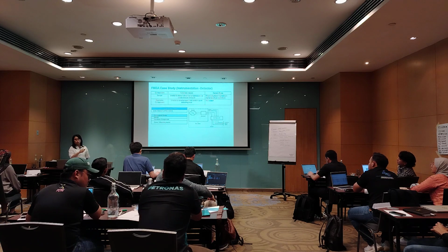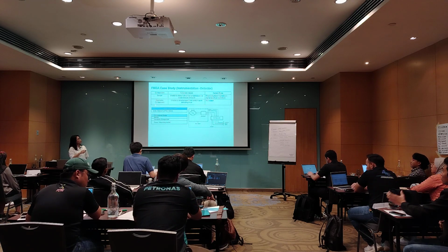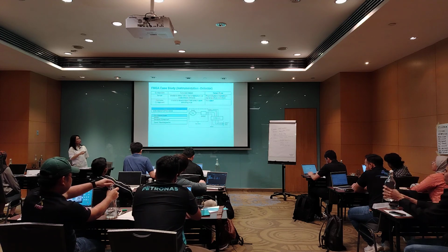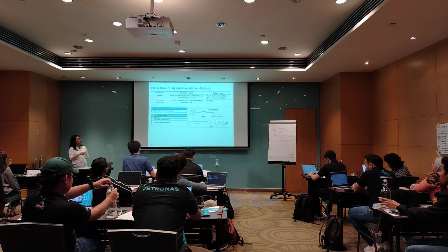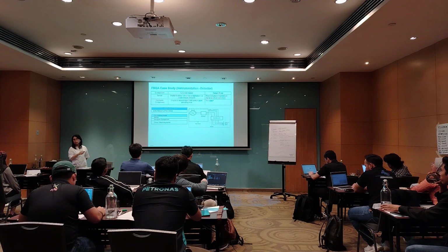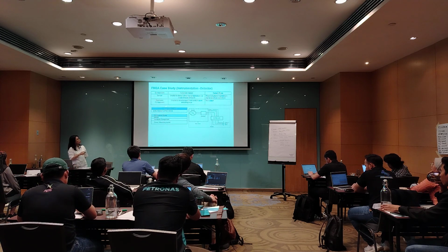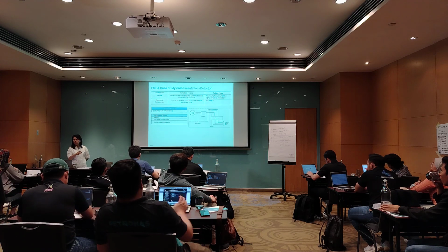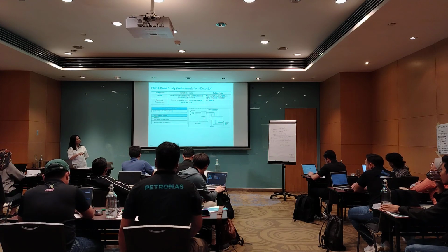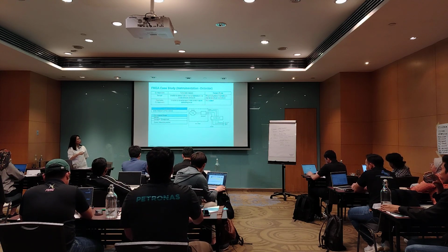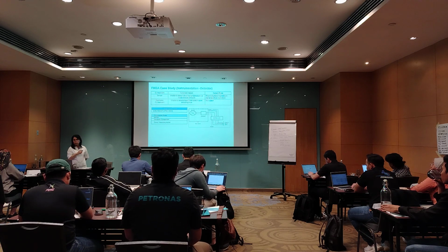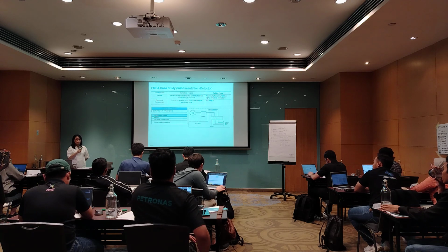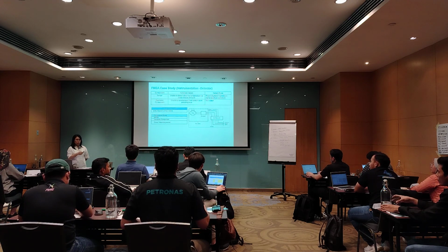Detectors. You have 2 components here, sensor and electronic component, unable to detect abnormal temperature. Failure mode is fail indication. Signal, unable to receive input, and then the failure mode will be no output. This is your equipment boundary. This is your equipment description as well as your components inside your boundary. You will need this during your FMEA. You need this to collect the data first.